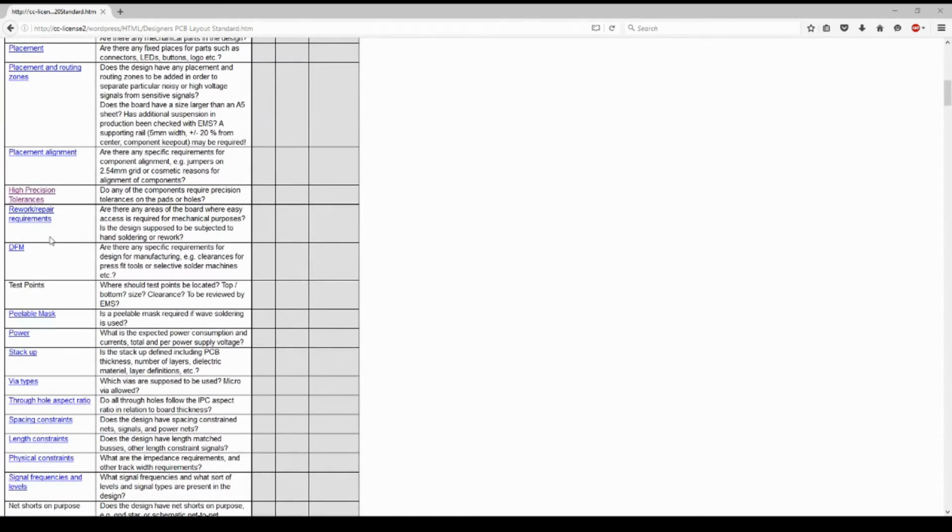Sometimes we have a lot of connectors that are identical, and it would really look stupid if they are placed in some kind of random or arbitrary way over the board. So we think about how we can align things more from a cosmetic point of view. Also there could be jumpers that are mounted identically, or maybe instead of several small jumpers, you could use a pin header. So figuring out how to do the alignment.